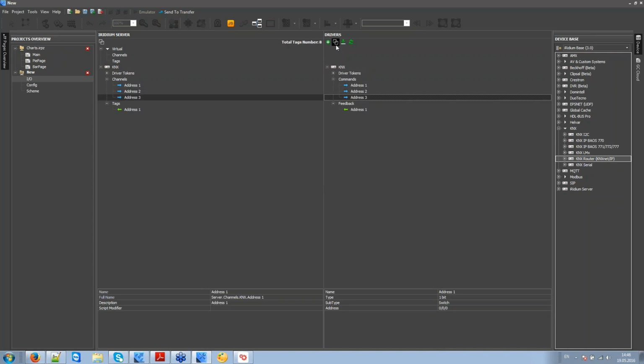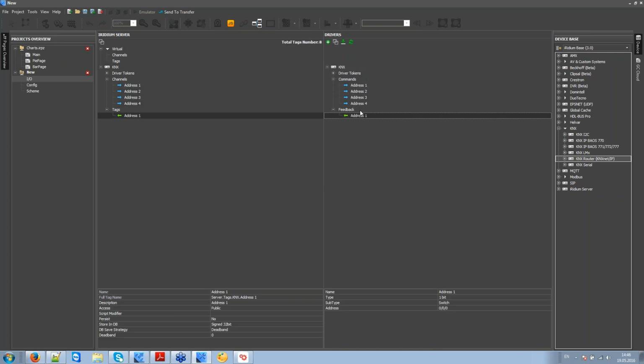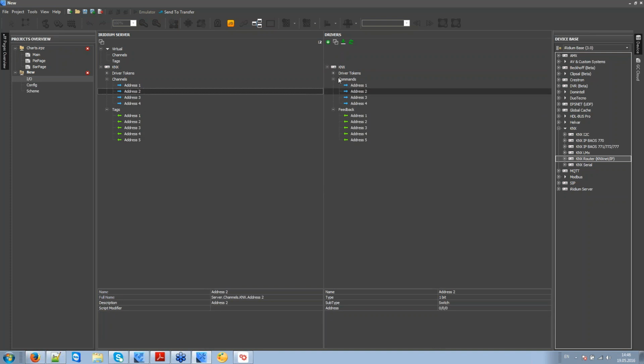Here I can set up the group addresses, the real group addresses of KNX, and these addresses will be displayed in the Iridium Studio tab as a projection of real addresses of equipment to the virtual variables of a server. Iridium clients will ask for the status of KNX from these variables, from the left tab.